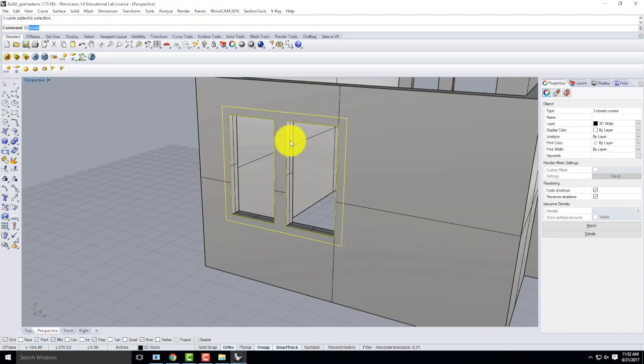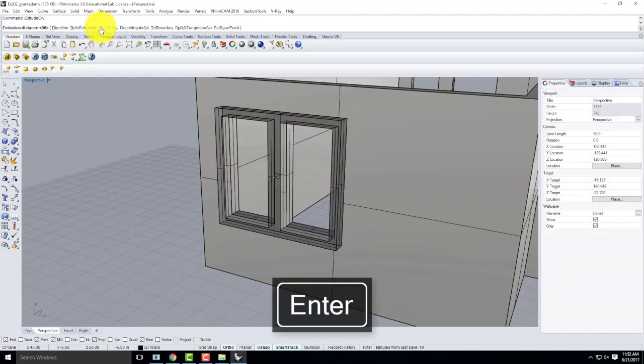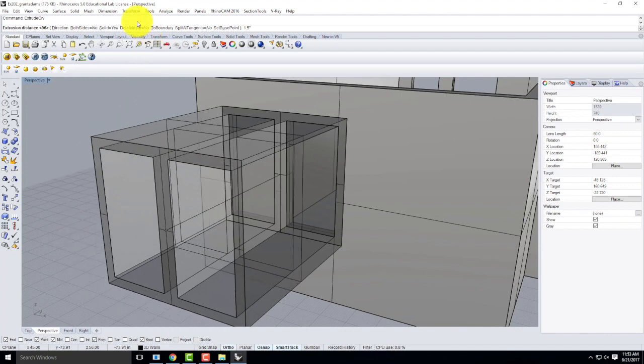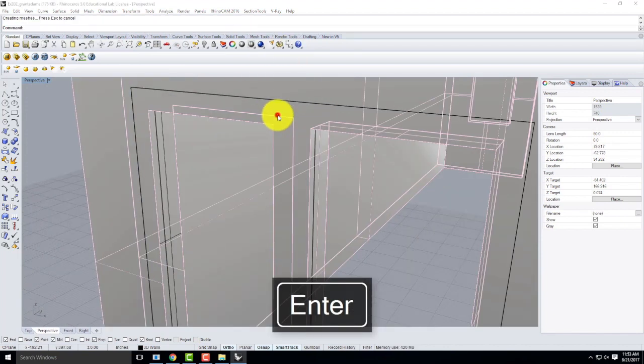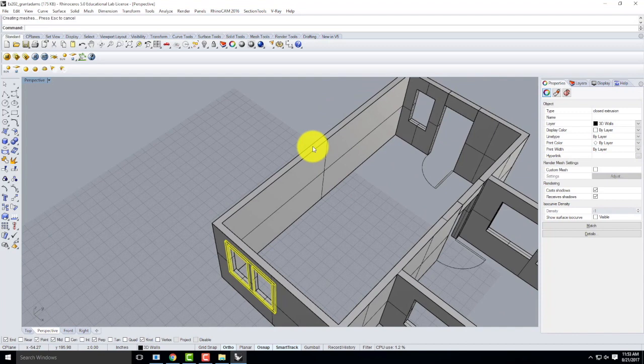So let me go ahead and just extrude curve. In this case, I do want it to be a solid. Yes, I don't want it to be both sides. And I want to specify how far. It will be 1.5 inches. I do want it to delete the input, so I'll go ahead and choose delete input. And oops, 1.5 inches. And it keeps doing it backwards. Because I'm going negative y instead of positive, I should have typed negative 1.5.